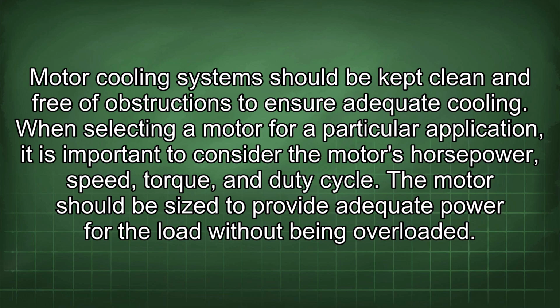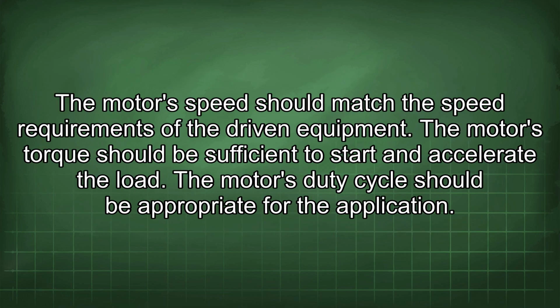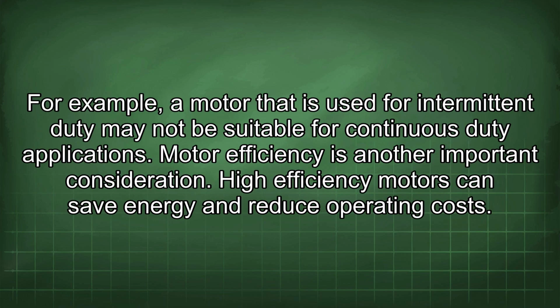When selecting a motor for a particular application, it is important to consider the motor's horsepower, speed, torque, and duty cycle. The motor should be sized to provide adequate power for the load without being overloaded. The motor's speed should match the speed requirements of the driven equipment. The motor's torque should be sufficient to start and accelerate the load. The motor's duty cycle should be appropriate for the application. For example, a motor that is used for intermittent duty may not be suitable for continuous duty applications.